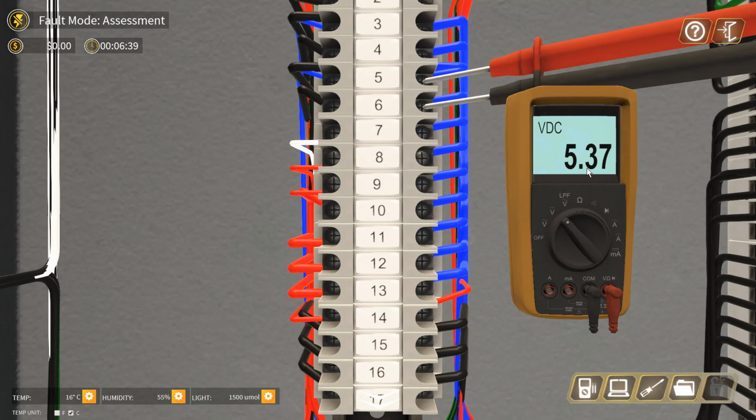Why? Because the DC voltage signal at the PLC analog input side must always be from 1 volt to 5 volt. It cannot be more than 5 volt nor lesser than 1 volt. Okay, the instrument may send a 4 to 20 milliampere signal to the PLC analog input. At the PLC analog input, this analog current will be converted to analog voltage of 1 to 5 volt. Subsequently, it will be converted from analog voltage to digital value through the ADC converter.